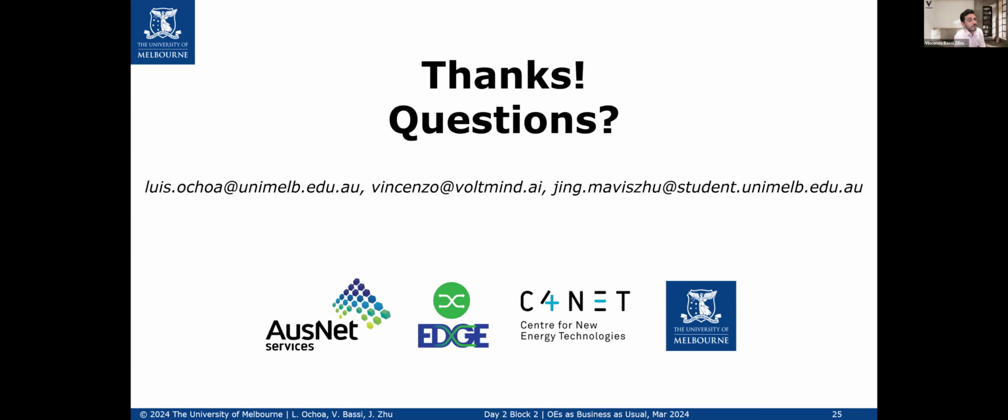penetrations, right? Tim is asking Vincenzo, is the breakdown of non-flexible and flexible customers valid? Realistically, all customers have essentially inflexible loads. Well, yes, I guess there is a confusion in here. When we spoke about non-flexible customers, those are customers that are not subject to the DOE. So for instance, they have fixed export limits as before. And those flexible customers are those that are subject to the flexible export limits or dynamic operating envelopes.